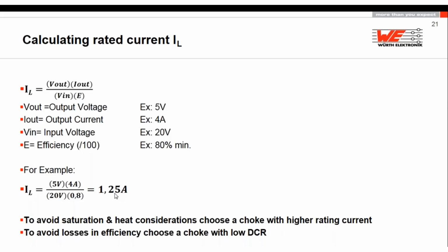Okay, if sometimes the size is too big because of the currents, you have to take a compromise and go down, but never ever go below 80% efficiency, because if you build something today which is less than 80% efficient, save the money for the switching, take a big resistor and burn the energy away. So 80% minimum is, for today, a minimum request. I know many companies that don't admit anything below 90% efficiency for a DC-DC converter. But come on, 80% is easy going today.